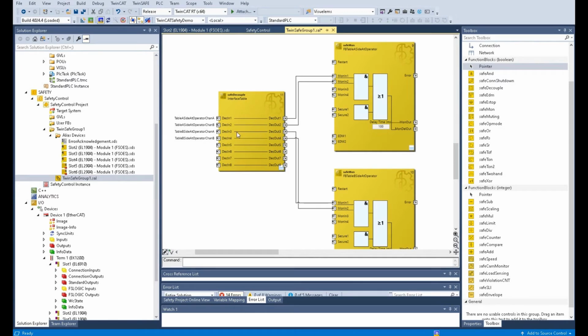It can be used like a buffer and can also be used like a group. For example, if your system has 4 light curtains, all the light curtain tags, interface tags, you can group here and use this outside to transfer to different function blocks.